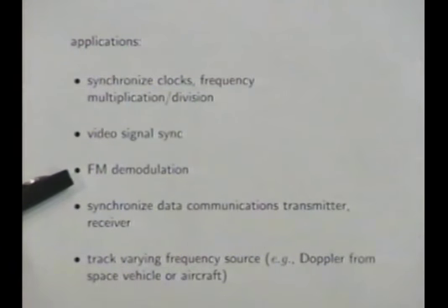Okay? So what that means is when you're listening to an FM station, the RF signal is basically 88.1 megahertz, and then plus minus, and then there's a few zeros, and then all the signal is in the fourth and fifth digit of that frequency. So what you are listening to is very, very small variations in frequency of a signal which is around 100 megahertz. And the way that's decoded is using a phase lock loop. In an FM receiver, you have a little phase lock loop that locks onto that frequency, and you look at the voltage that's telling the oscillator what to do to track the incoming frequency, and that's your audio signal. So that's how that works.